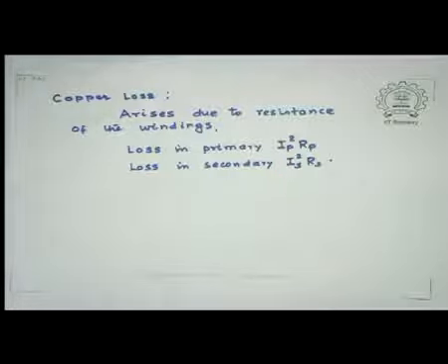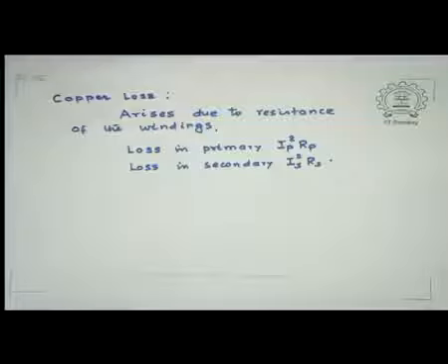So notice that both these losses depend upon the current that flows in the primary and the secondary circuit, and so therefore such losses depend upon load.